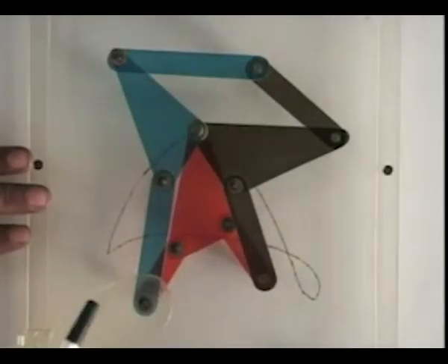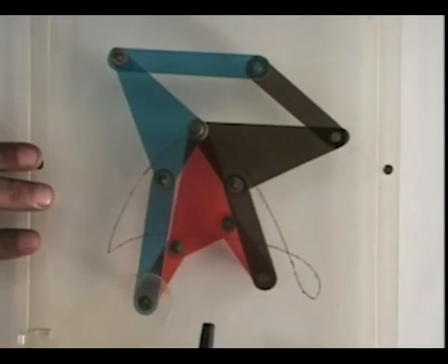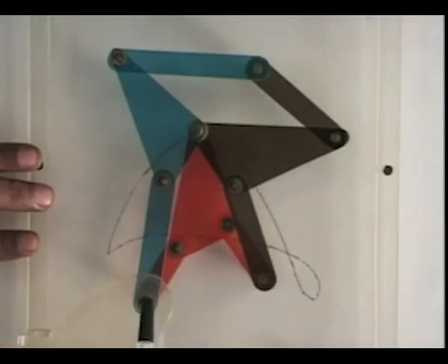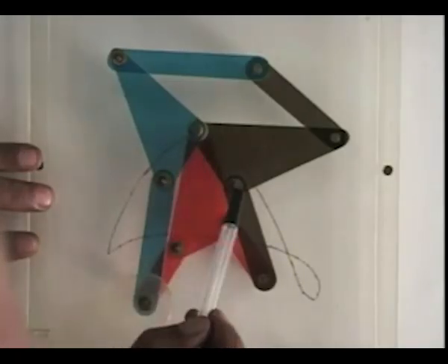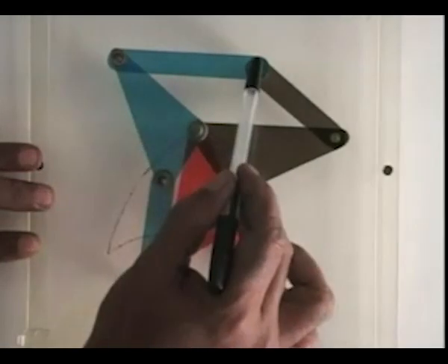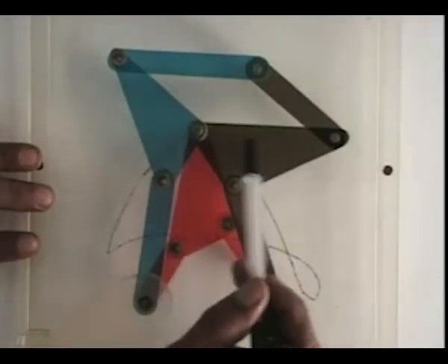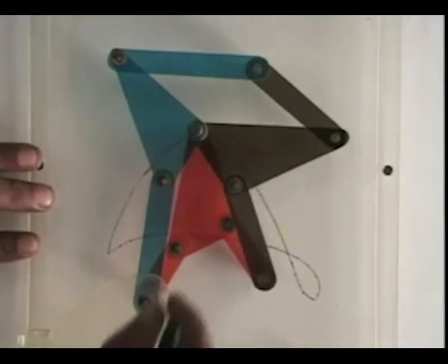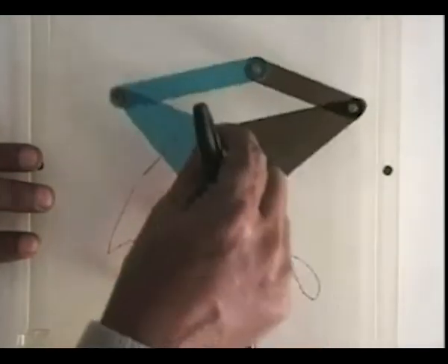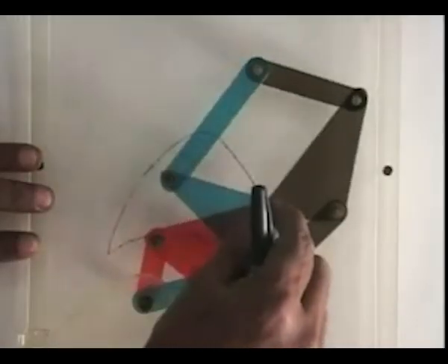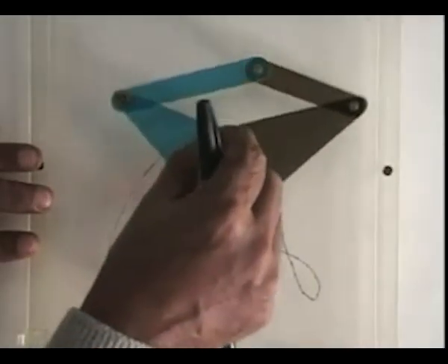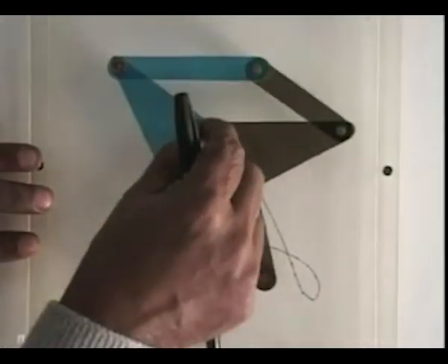Let us now look at the model of this 10-link mechanism which has just been discussed. As we have seen, according to the calculation, the degree of freedom should have been minus 1. But notice that these 4 hinges constitute a parallelogram, so do these 4, and these 4 hinges also constitute another parallelogram. And these 3 triangles, the ternary links, are similar to each other. Consequently, this constitutes a single degree of freedom mechanism which is an overclosed linkage which has mobility. It is not a structure.